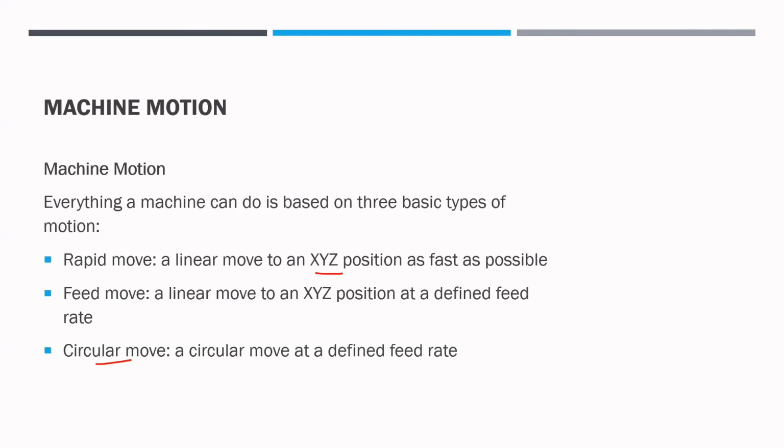X and Y are Cartesian coordinates for horizontal and vertical position, and Z represents the depth of the machine. These alphanumerals will follow the motion function G to declare the position of the machine.